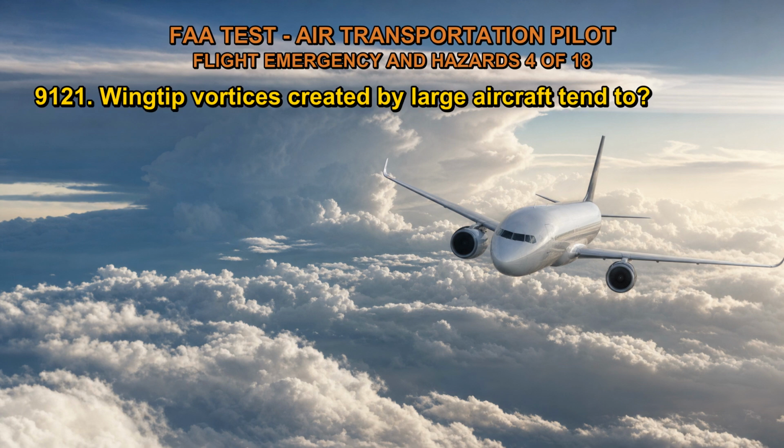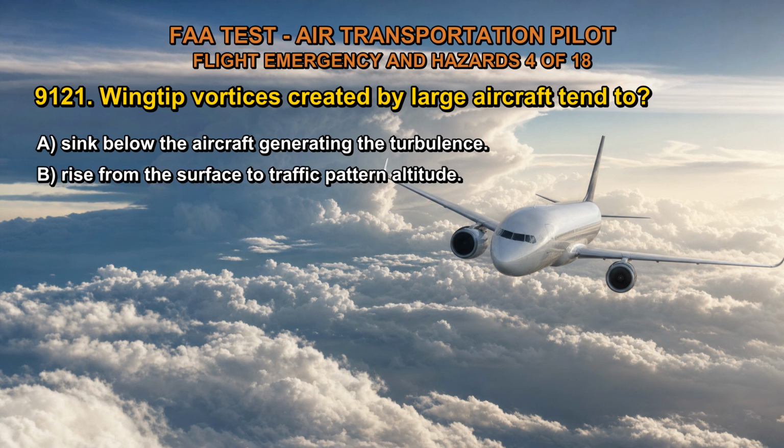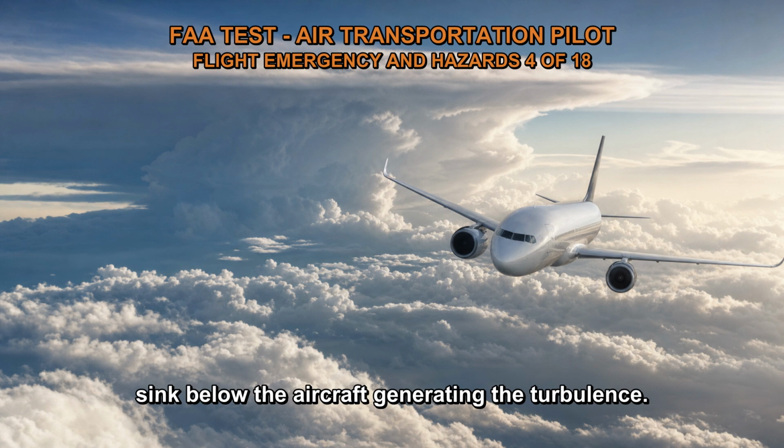9121. Wingtip vortices created by large aircraft tend to A. Sink below the aircraft generating the turbulence. B. Rise from the surface to traffic pattern altitude. C. Accumulate and remain for a period of time at the point where the takeoff roll began. The correct answer is A. Wingtip vortices created by large aircraft tend to sink below the aircraft generating the turbulence.